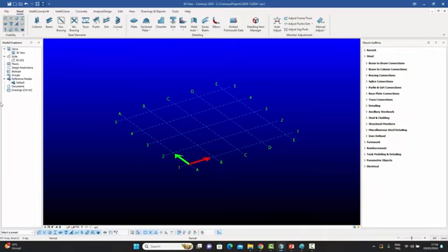If you look at the left hand side, we have our tree view. And if you remember, we had these groups, and now we have this thing called reference models over here. This wasn't present in the earlier versions. Under the reference models, we have a default group. When you open a new model, you will have that over there, and you can use that to subsequently import any reference models. Now we will talk about the details of how you do that. So let's start with that.